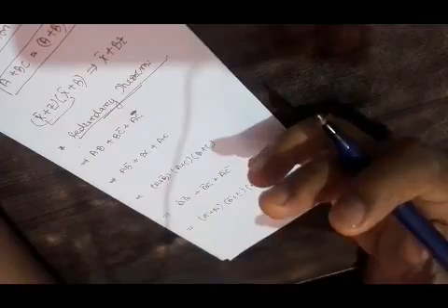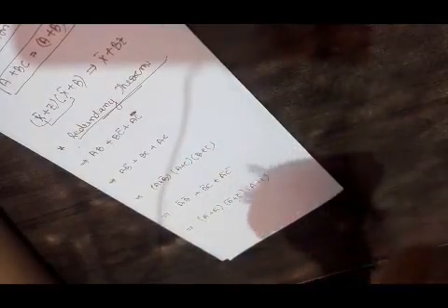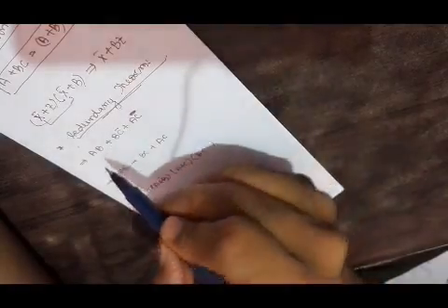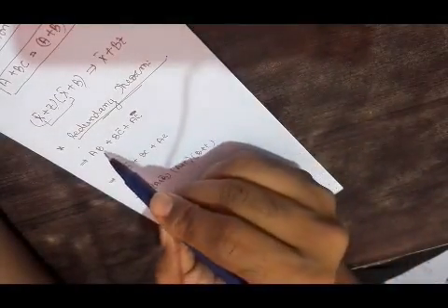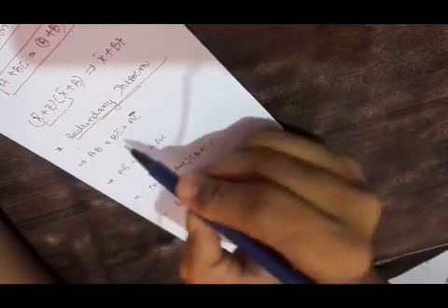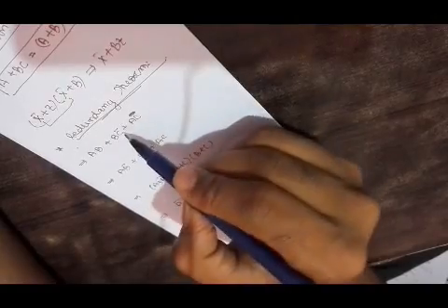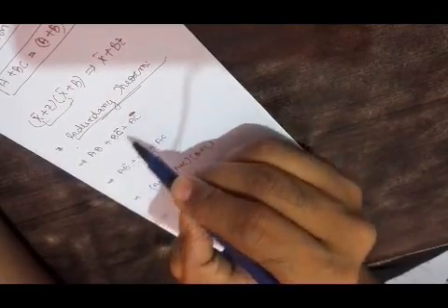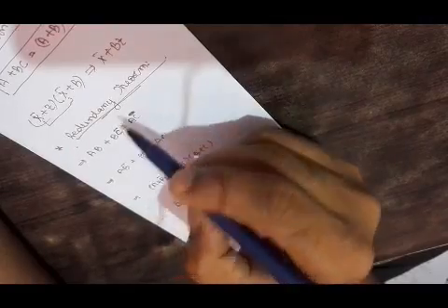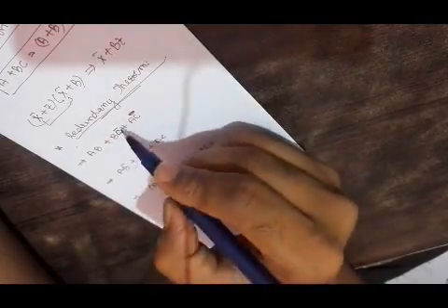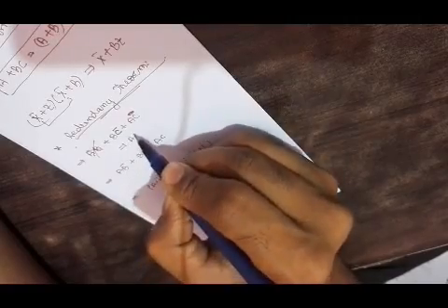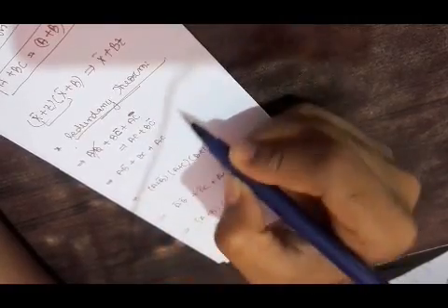If this pattern is followed, now you have to check only one thing: which term is the redundancy term in these expressions. So you see that here C is showing some variations. Here the C term is showing some variation. We have C' and we have C. Okay, so these terms are mandatory because they are going through some changes. So what is the redundancy term? Except these two terms, this is the redundancy term. So this can be written as AC + BC'.